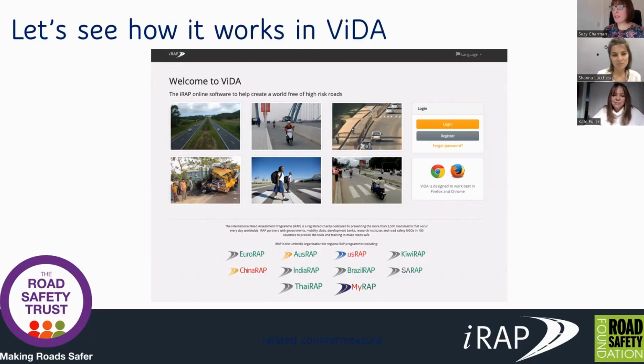Yeah, and actually some of what the iRAP model was doing in the urban environment was very much about segregating pedestrians and cyclists from motorised traffic. But what we've tried to do in this project is to talk about making road environments more holistically suitable for mixing pedestrians and cyclists and motorised traffic. So actually the emphasis now will be less on grade separated pedestrian crossings and pedestrian guardrail, but more on the sort of holistic approach to the road environment to make it more suitable. I hope that helps.